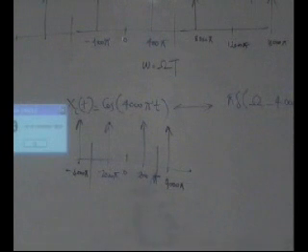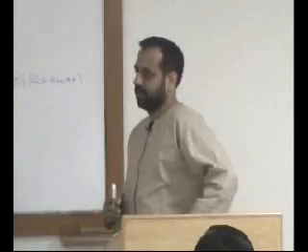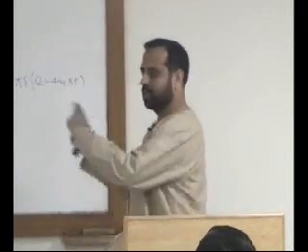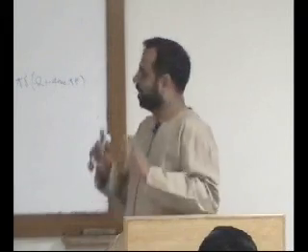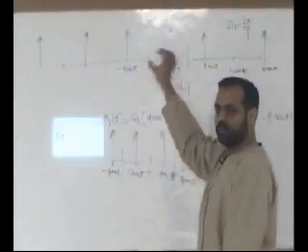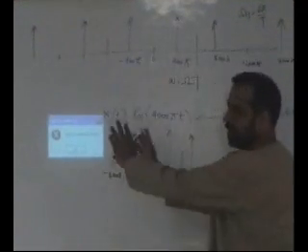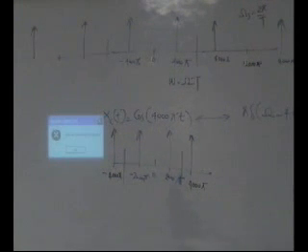So a sinusoid, if not sampled fast enough, will map to another sinusoid of lower frequency, and the lower frequency is equal to omega s minus omega naught. That is the relationship, and once you reconstruct it, you will get a cosine, but it will be a slowly moving cosine. And again, it's simple: you draw this, then make copies, preferably on a tracing paper, just consider minus pi and pi, and throw away the rest. That is your spectrum, the digital spectrum. If you convert it, you get that.